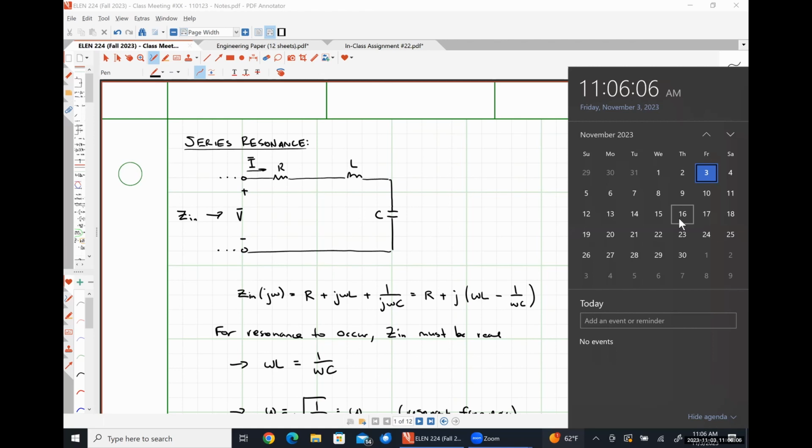Pretty much, yes. That being said, design project 1, if it takes you more than 30 minutes, you're doing it very wrong. Design project 2, also, if it takes you more than 30 minutes. No, I mean, so for design project 2, you're told where you need your pole and your zero to be. So just pick a value for the resistor and then do the math to figure out what capacitor values you need.